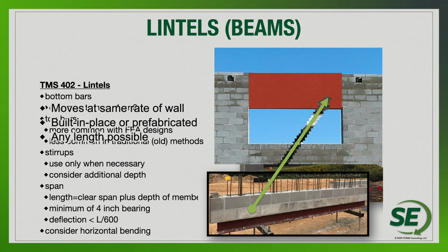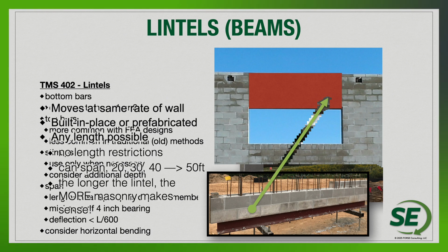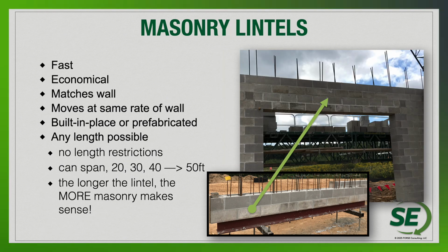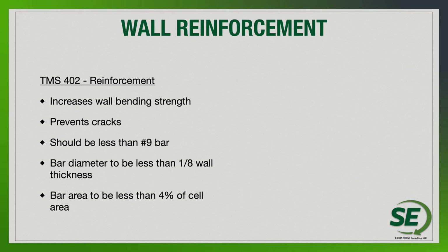There's not going to be anything within the code that's going to set any size restrictions, so there are no length restrictions. And really, honestly, the longer the lintel, the more it makes sense for the lintel to be masonry and not some other material. So we definitely know that masonry lintels are going to be a very good component of the overall masonry wall system design. Last little piece of information here is about code requirements for reinforcement.